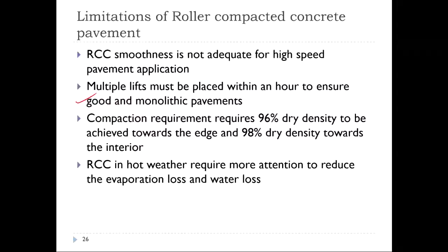The multiple lifts should be placed within an hour to ensure good monolithic pavements. Again, regarding the compaction requirement towards the joints, as I mentioned, it would be difficult to achieve higher levels of compaction. So the compaction requirements shall be 96% of the dry density towards the edge, and towards the interior 98% dry density. So this is slightly a higher requirement.